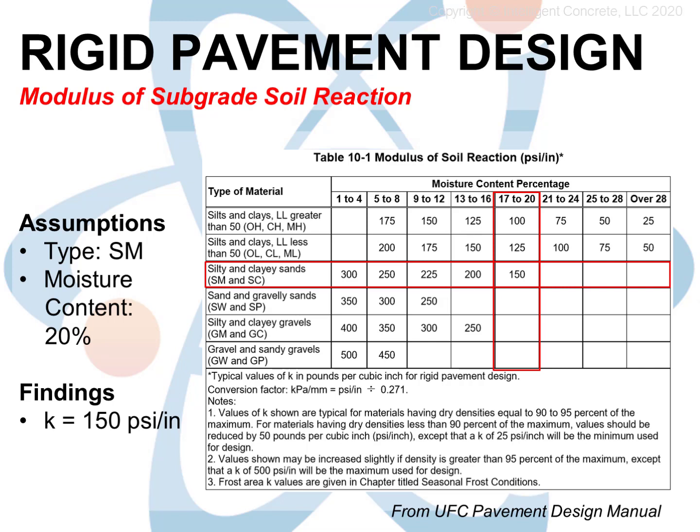The table shown uses soil types and moisture contents in percentages to estimate the K value. Tabular values are often good enough for estimating purposes and for designs of less critical surfaces or if laboratory testing isn't available. Critical pavements, especially those that are very extensive in scope, such as an entire runway, require laboratory tests to determine this value.